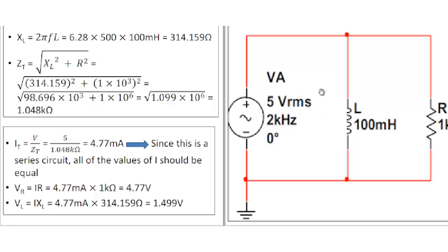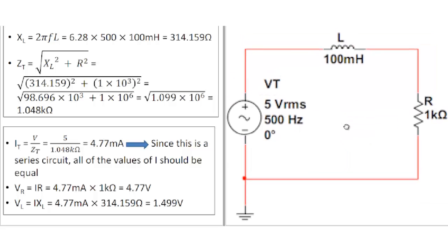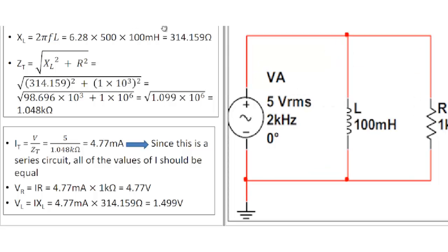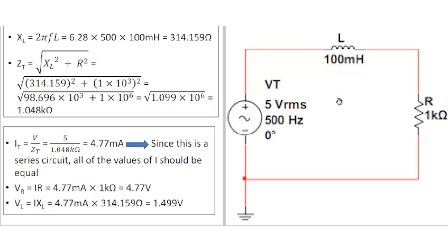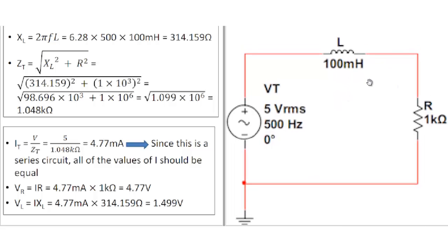And when you look at a circuit like this, this is going to be an example of a series LR circuit. A couple of questions should come to one's mind when you look at circuits like this, whether it's inductors or capacitors or anything. Ask yourself, what do the components in the circuit have in common? In this particular case, what these components have in common is current flow.